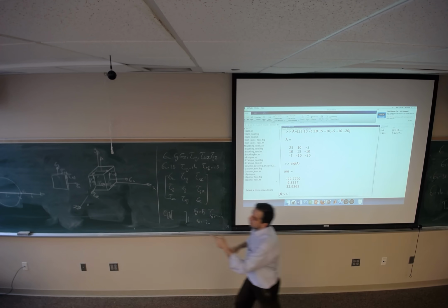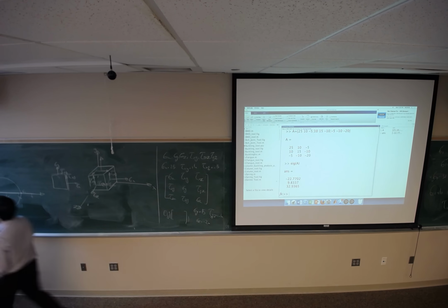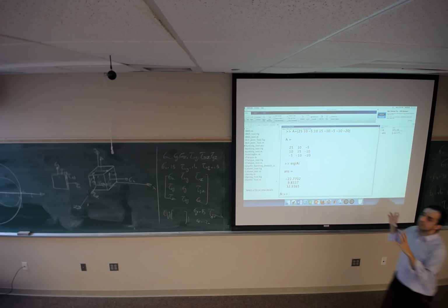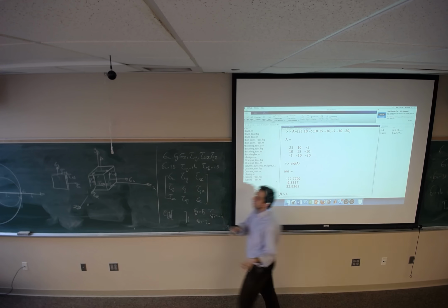Between sigma 2 and sigma 3, you can draw a circle. Between sigma 1 and sigma 3, don't forget to draw a circle. Something like this. So you will get 3 circles because you have 3 combinations: sigma 1 and 2, sigma 1 and 3, and 2 and 3.